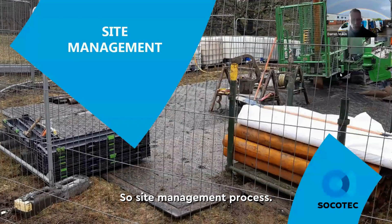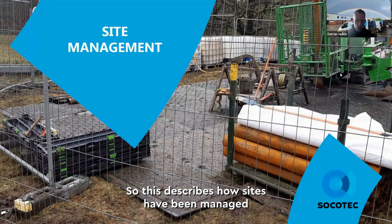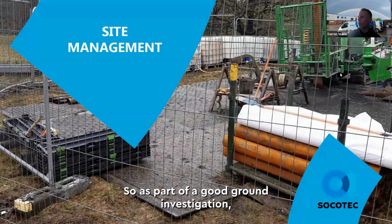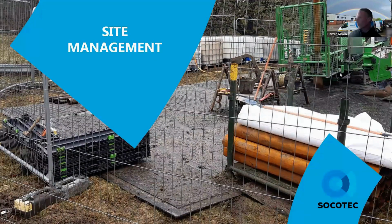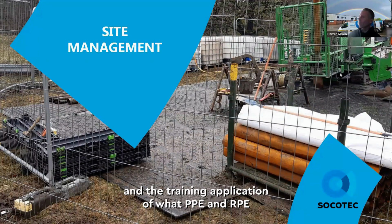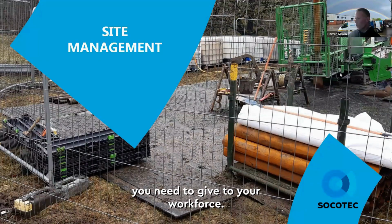So, site management process. This describes how sites shall be managed to inform the risks and prevent exposure. This covers induction. As part of good ground investigation, you induct the workforce on red site working, on the potential risks associated with the ground, and how you're going to mitigate it. This also describes the use of PPE and RPE, and the training and application of what PPE and RPE you need to give to your workforce.